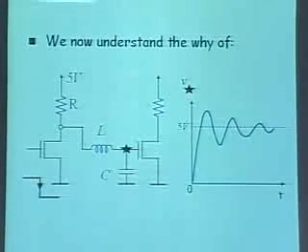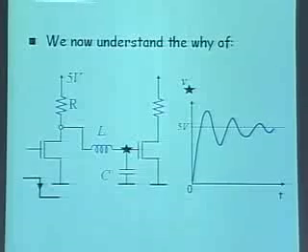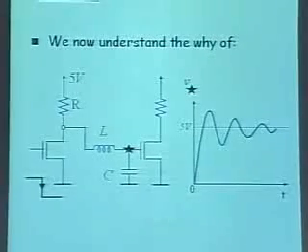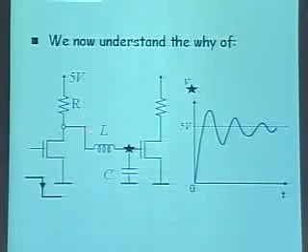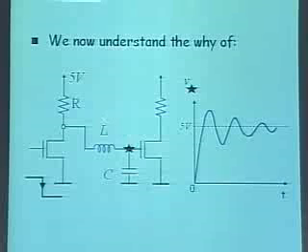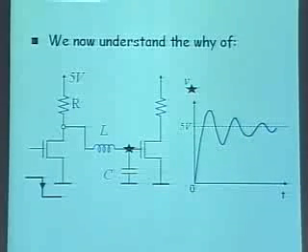And the inductor, an ideal inductor, looks like a complete short circuit for DC. So in the long term, this guy is a short, this guy is an open, so 5 volts simply appears here. And this is the transient behavior when we just switch the first transistor off.